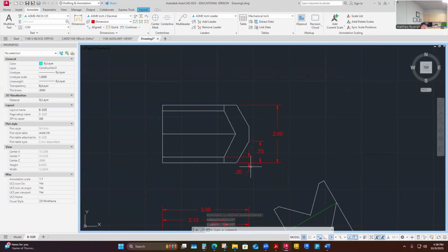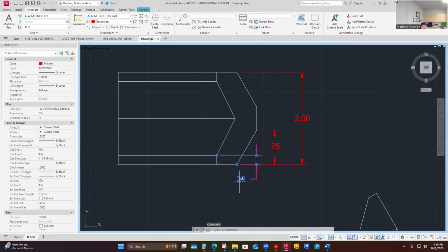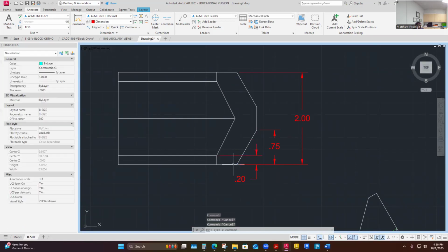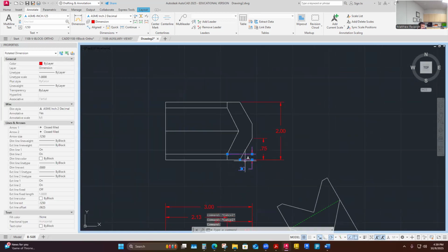I'm definitely pulling from the front, so I like that these are all pulling from the front surface. Should I do that there? That's 2 times that dimension so that it applies over here, or I could put that in as a reference dimension. I think in my mind, I'm really going to pull this dimensionally over to here, actually.